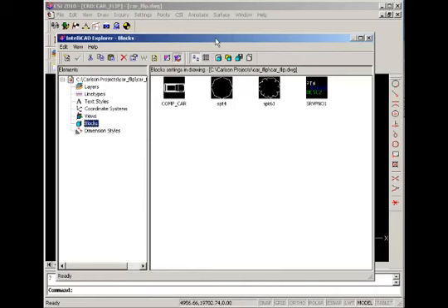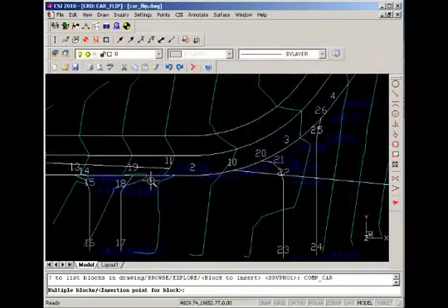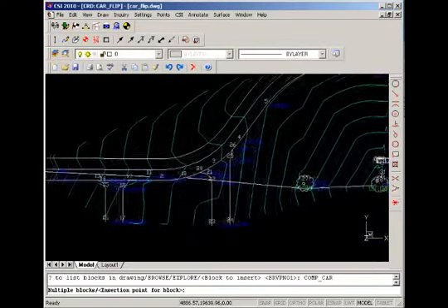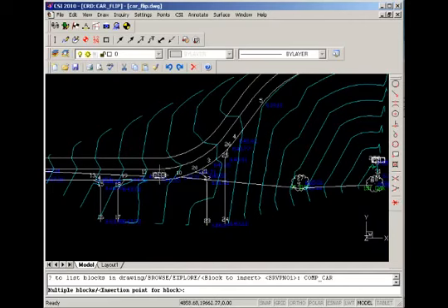Here's a block for compact car. We'll double click it, and we'll place it at the location where we went off the road here. We'll accept the default scales and rotation angle. We can specify by stretching the rubber band to the side.